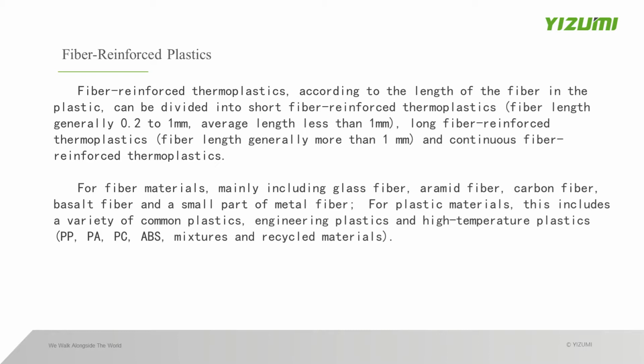Fiber reinforced thermoplastics, according to the length of fiber, can be divided into short fiber reinforced thermoplastics, where the fiber length is 0 to 1 millimeter and the average length is less than 1 millimeter, and long fiber reinforced thermoplastics, where the fiber length is generally more than 1 millimeter.